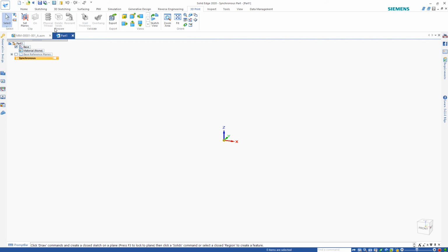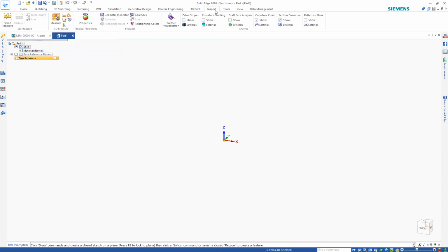For example, I know there's one thing that bothers people a lot: when they use CAD software to generate a design with a thread hole on it and want to 3D print it, they find out that all the thread holes are just normal round holes. Here under the 3D Print tab, we have Physical Threads, which will help you generate an STL file with real physical threads inside, which I think is a pretty useful function that helps you print out the final useful product.